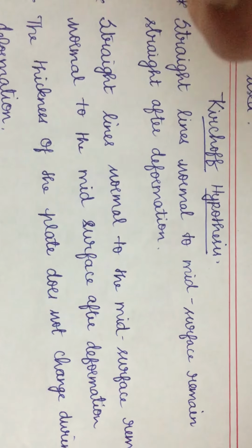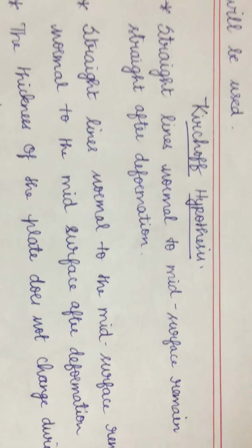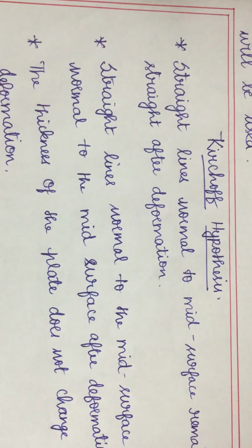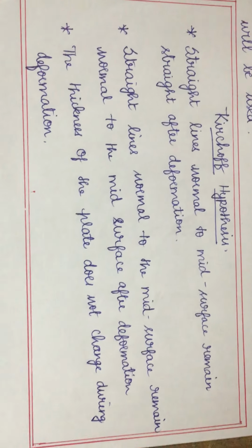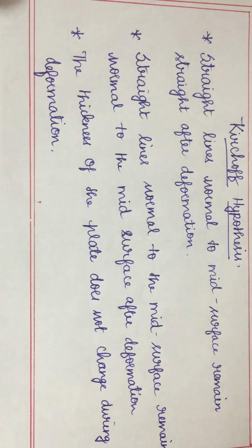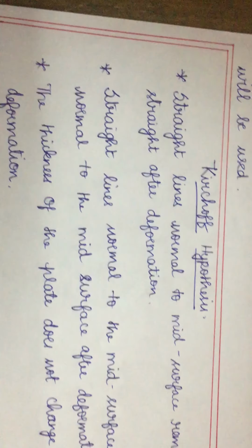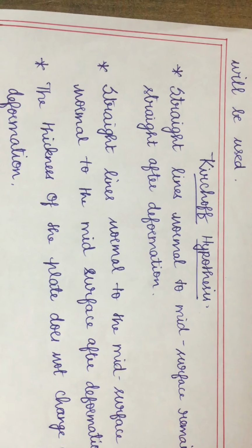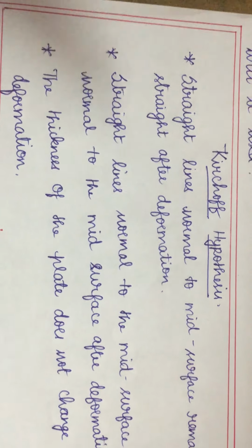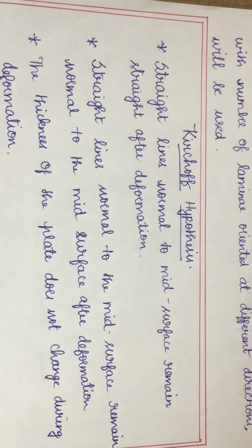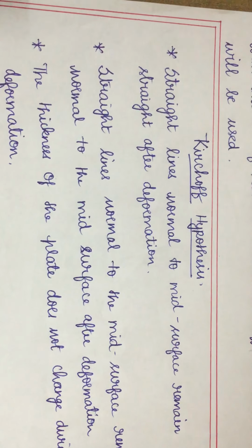Straight lines normal to the mid surface also remain normal to the mid surface after deformation. So if the surface is deformed, the straight line will always be normal to the mid surface. It will not change even though the laminate is deformed.